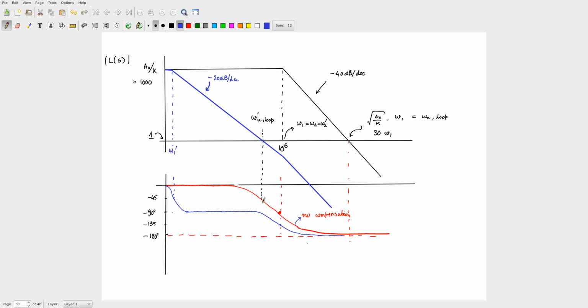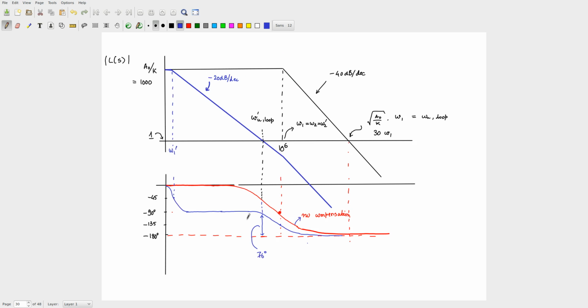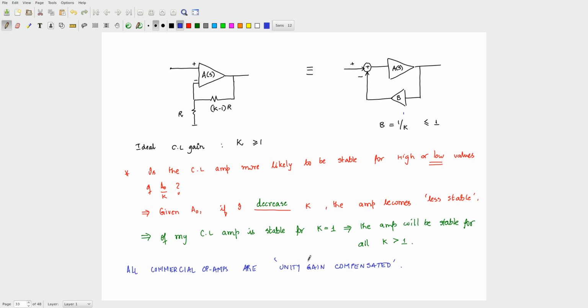And that's why if you now look at the loop gain or the unity loop gain and look at the phase margin, we have already calculated how much should this approximately be, around 76 degrees, because we in fact did the compensation, if I remember right, for zeta equal to 1. That's how we started, no, we wanted zeta equal to 1 and we did this, right. So this is the guy with compensation. Okay, I remember this somehow, I don't know why. Anyway, let's proceed.